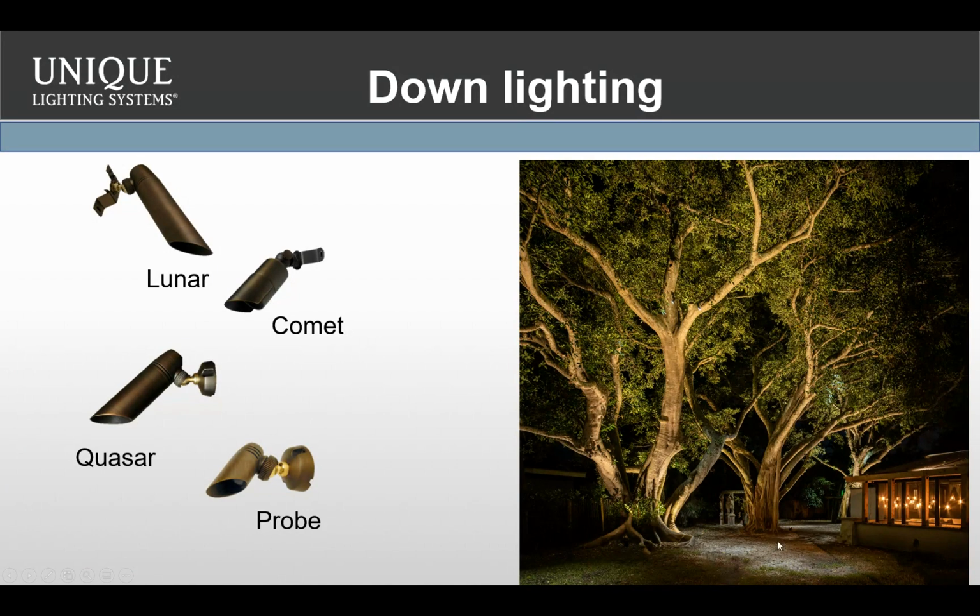What's nice about this is there's no defined edge, so there's no place to put any path lights or bollards. Had we not done this, over time the homeowner or property owner probably would have put a big spotlight right here and glare-bombed this whole thing, and it would not have been a comfortable space. So I've got a nice comfortable atmosphere on the ground, and we've put these at 5,000 Kelvin. It's a much cooler color temperature that gives me that silver moonlight on the ground. So this location gets a full moon effect 365 days a year.